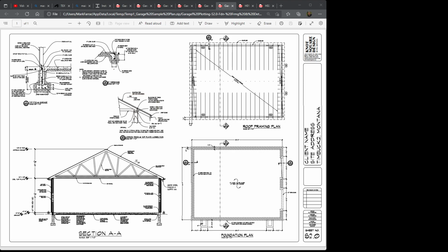So there's the connection. We covered this one at the door opening, and then for the rest of the footing, we do have this standard footing detail. And like I was saying, you see the design criteria to get the depth. So I could add it to the story pole, and I actually just realized that it's see the design criteria. A lot of these tell me to see the section. So it is covered, because in the design criteria, it actually tells the frost depth. So it doesn't need to be redone.